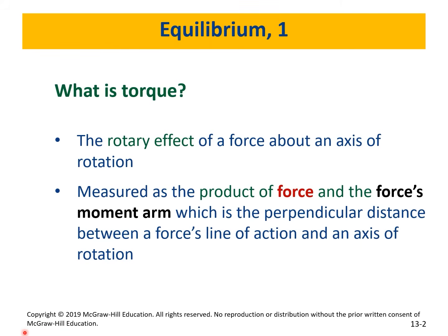So torque is moment, that's what you learn in statics and dynamics, and we try to avoid moment because we have momentum, but that's force multiplied by velocity. So the most important thing is that you're going to multiply force with the distance, but the distance needs to be perpendicular to the line of action of the force. We good with this? Okay.